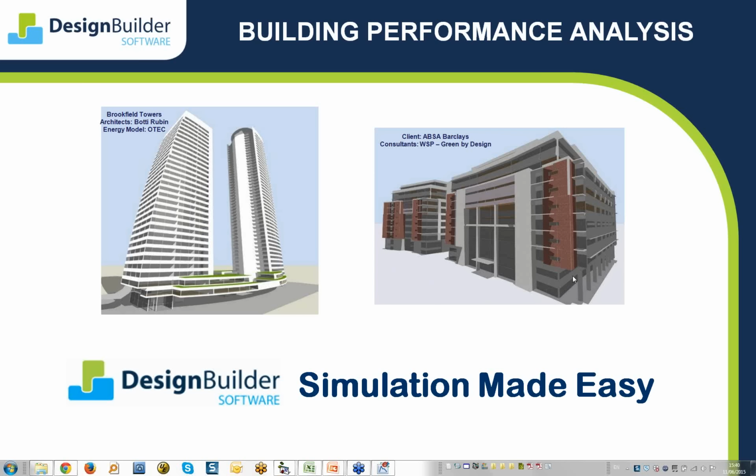Because that maps very nicely to the DesignBuilder block concept, and also because we can import the thickness of those constructions, provided the model is set up correctly in Revit, you will get an identical representation within DesignBuilder, because DesignBuilder can identify the thickness of each surface from Revit through the construction.